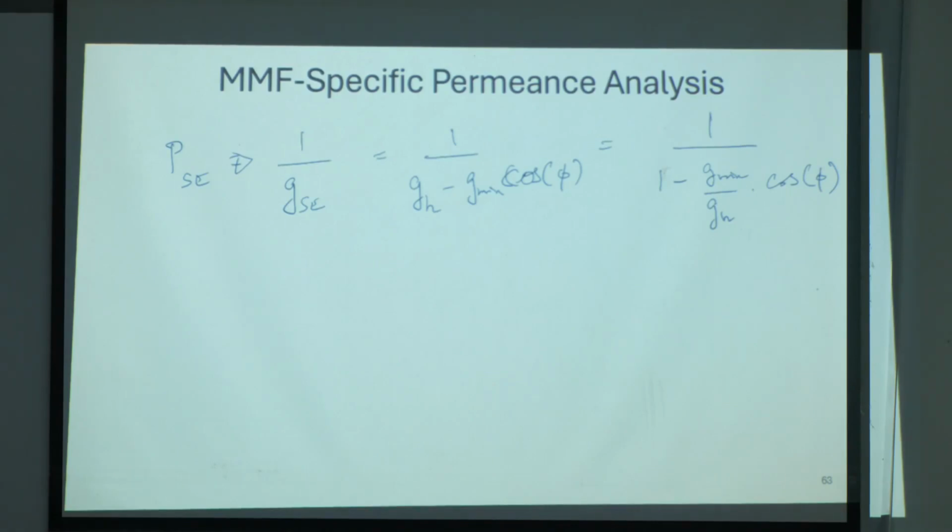Now let us look at boundary conditions. When there is no static eccentricity, what is the value of G min? What is the minimum air gap you can have? So this G min is the point, right? When there is no static eccentricity, G min vanishes, so this becomes 0. If this is 0, then only we can say that there is no eccentricity. So under healthy condition, G min is 0.